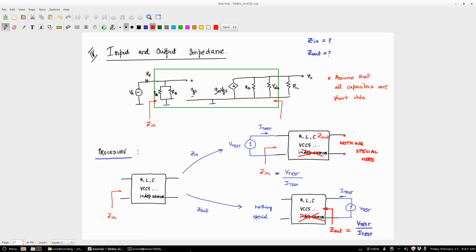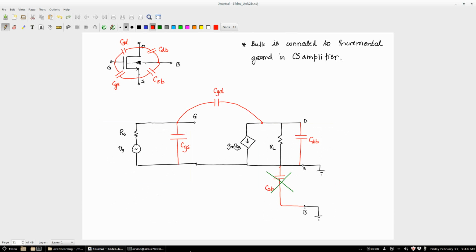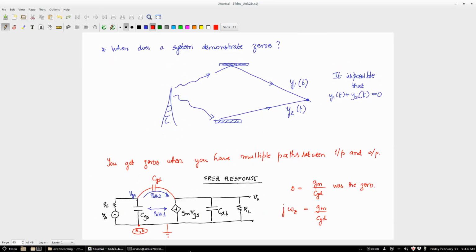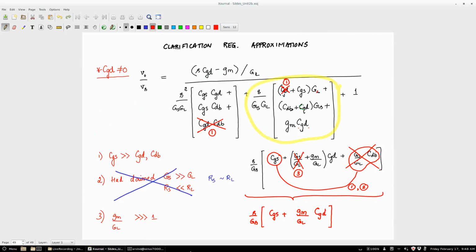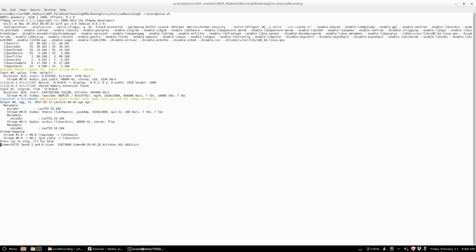We will do 6 topologies. The common source amplifier with MOSFETs. Very similar is the common emitter amplifier with a BJT. Okay, that I can just do in like 10 minutes. Then you will have a common drain amplifier, which is similar to the common collector amplifier. You will have a common gate amplifier, which is similar to the common base amplifier. Then the op amp, which will have many amplifiers cascaded together. So the goal of this course is to teach you how the internals of an op amp will appear. And you will see all of the stability we talked about, all of those things will appear. Okay, we need to go much faster.